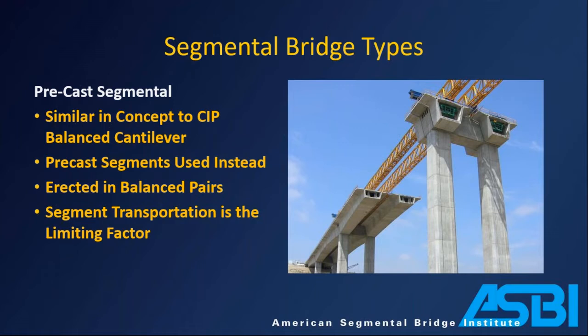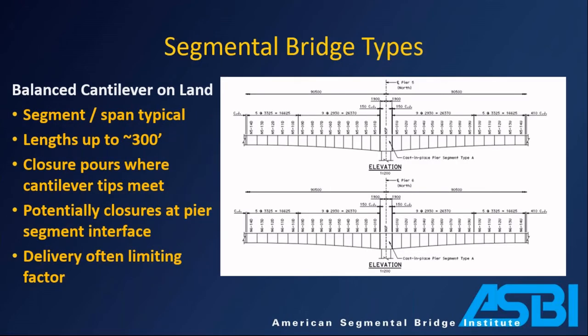The big thing with these is transportation weight. And that's really the limiter on what you can do with these in terms of span lengths. So this is one that was done on land, and roughly speaking, they can be divided into delivery by land, taking things over highway, and delivery by water. When you're delivering by land, typically kind of limited to about 15 or 16 foot depth, and that's going to reflect itself in limitations on your span length somewhere up to around 300 feet.